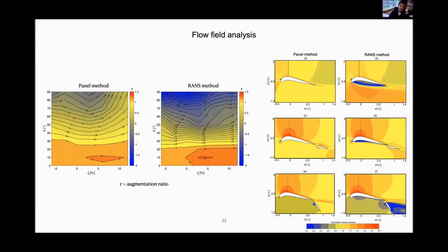We noticed that with the increase of theta, there is a performance drop, but with an increase of zeta, there is a performance increase. So there appears to be a sweet spot somewhere, which gives me optimal performance for the multi-element duct configuration. So you need to have some optimization study before trying out different configurations.